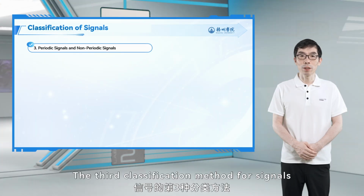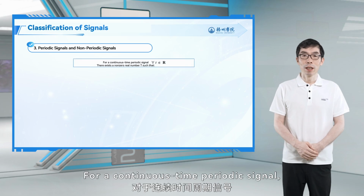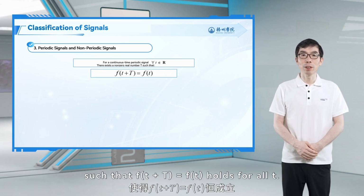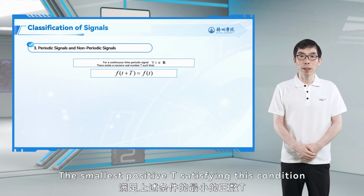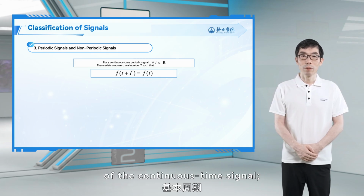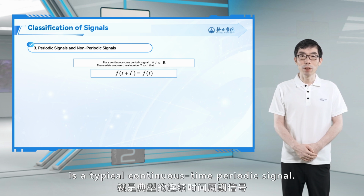The third classification method for signals is periodic signals and non-periodic signals. For a continuous time periodic signal, there exists a non-zero real number T, such that f of t plus T equals f of t, holds for all t. The smallest positive T satisfying this condition is called the fundamental period of the continuous time signal. For example, the sinusoidal signal mentioned earlier is a typical continuous time periodic signal.